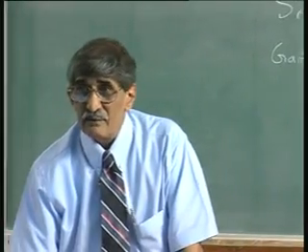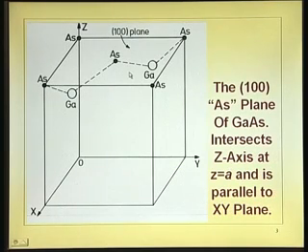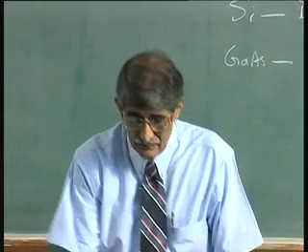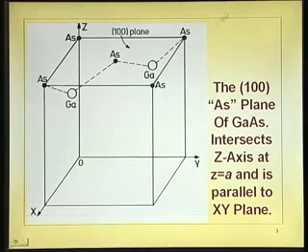Okay, this is the structure, thin film structure. Now, let us take a look at further. In fact, these will be lying on the main diagonal, these atoms, when you go up from here to there. Let us take a look at what are the different planes. I just removed all other atoms now from that cube, same cube, cleaned up everything, I have retained only the top surface. If you take a top surface, I have marked it as 100 plane.